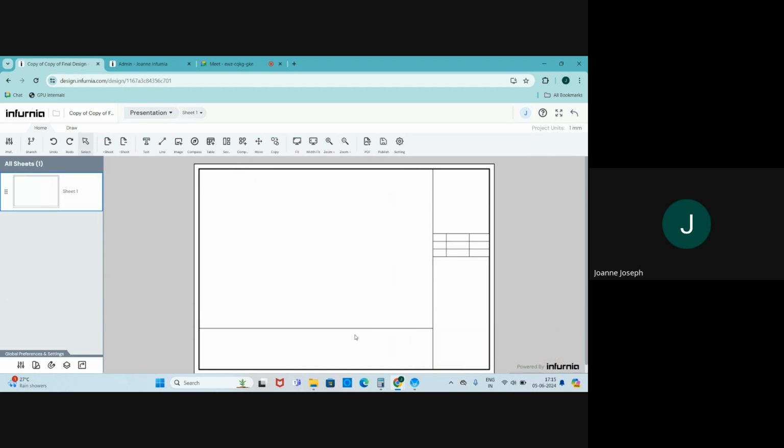However, you will have to delete the one you've created last because none of the lines depend on that. So if I click on this and in the left hand panel, I select remove section line. And now if I click on this and remove section line, this is how you can delete section lines. You cannot delete it in the normal way. Just bear that in mind, unlike a line, which you can.